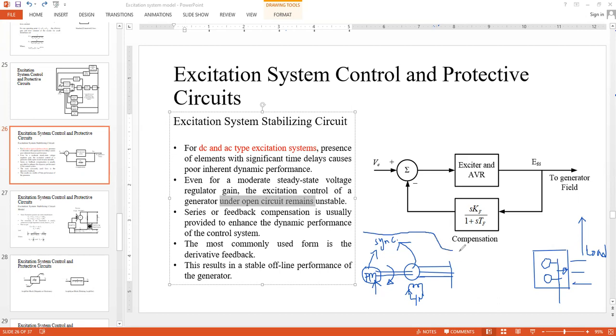Throughout all this operation till now, you haven't actually connected your generation output to the bus bar to supply the load demand. What you are simply trying to do is bring the machine to synchronous speed, and also make sure that the line to line voltage here, let's say if you measure it with the voltmeter, is 440, that means the voltage available at this bus from this generator should also be around 440 or exactly 440 in magnitude. So you are also making sure that the voltage is 440.